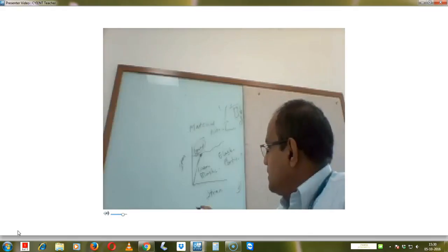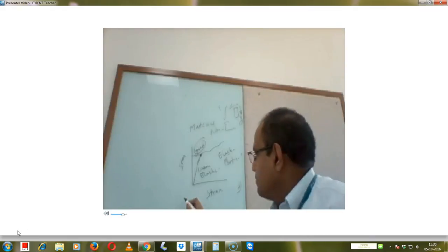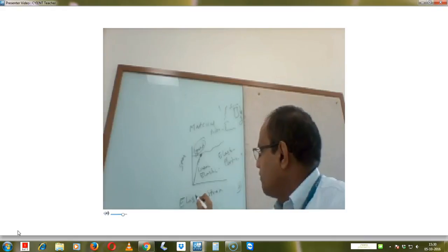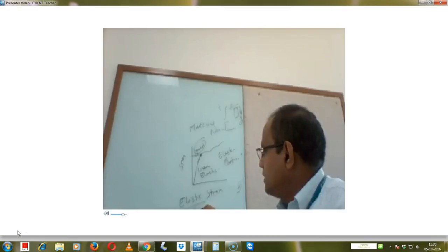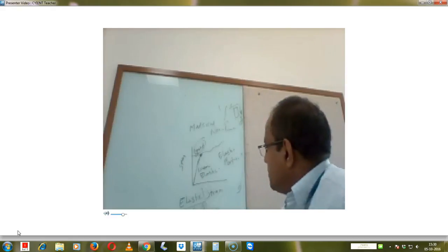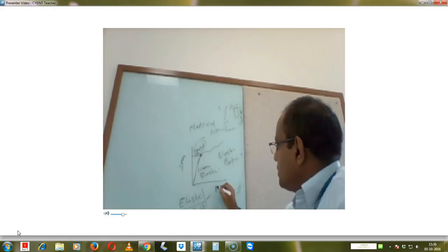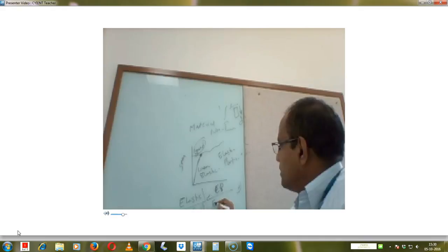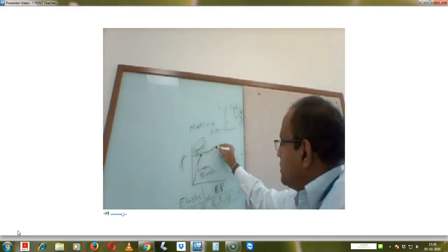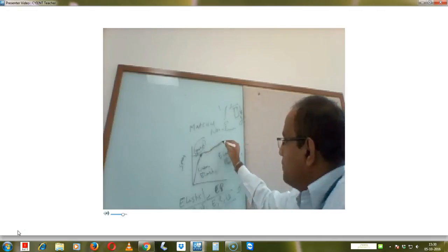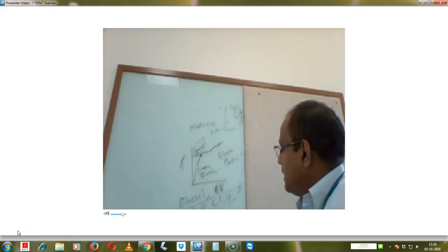Here in elastic condition, we give only Young's modulus, density, and Poisson's ratio. Whereas in plastic condition, elastoplastic, we give Young's modulus, density, Poisson's ratio, and we also need to give this information. We have two ways of giving this information, that is bilinear or multilinear.